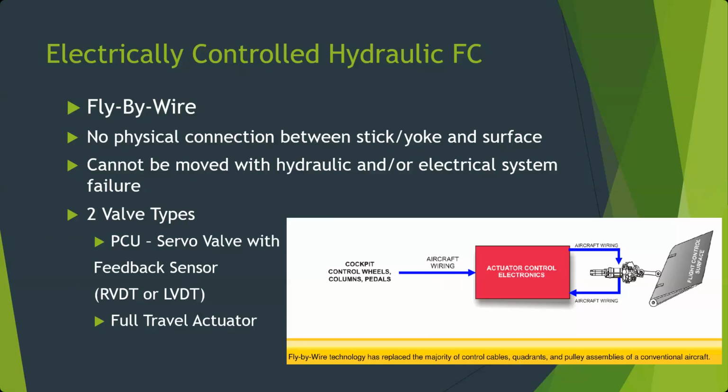So they're going to sense how far you turned the yoke for the ailerons, how far you pushed the rudder pedals to move the rudder, and so on. How far did you move the steering tiller to turn the front wheels when you're on the ground? That can even be a fly-by-wire. It's not flying, but it's called a fly-by-wire system when you do that.